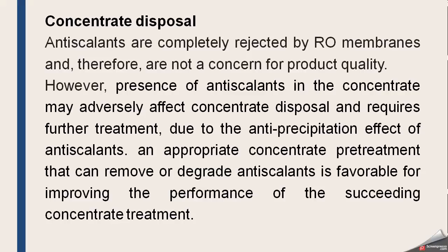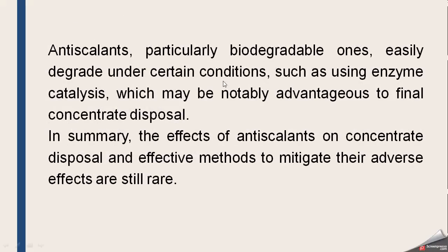and so the water which is disposed of must not have these antiscalants present. So an appropriate concentrate pretreatment that can remove or degrade antiscalant is favorable for improving the performance of the succeeding concentrate treatment. So antiscalants, particularly biodegradable ones, can easily degrade under certain conditions, such as an enzyme catalyst.